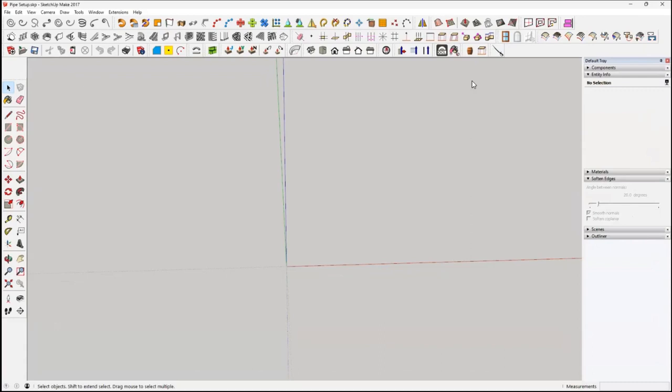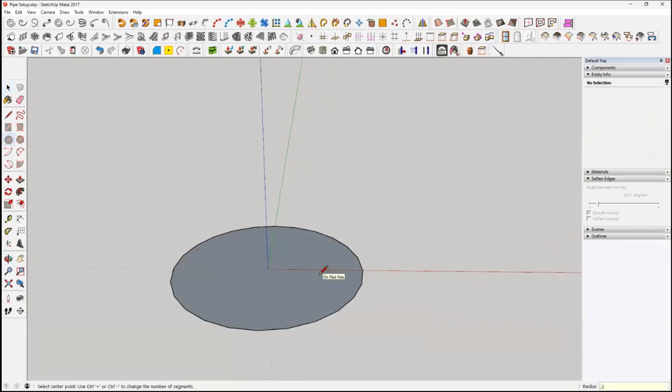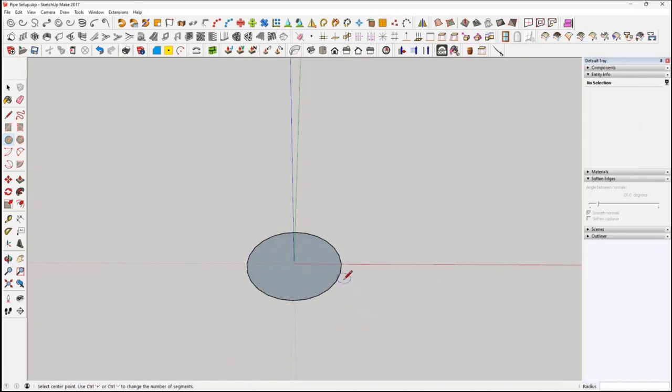So in SketchUp again, the rod was 4mm, I think. So right, draw a circle right in the origin along the red axis. With 4mm, so it's 0.2. And that'll give me a 4mm inside. We'll click on the circle, we come up to the entity info, tells you there, radius 0.2, and the segments. Up the segments to 40, and gives you a bit of a smoother curve.